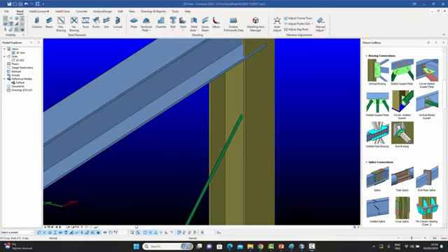Now let's consider this situation. This is the fourth macro which we've developed for you in this version. Usually, whenever we have significant seismic forces or significant wind forces, you never do something like this. You don't use these flimsy rod profiles as your bracing. But when your loads are really low and all you need to do is just make the structure stable, take a little bit of load, then it is common practice to use these rods as bracings.